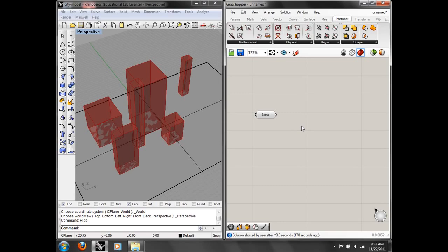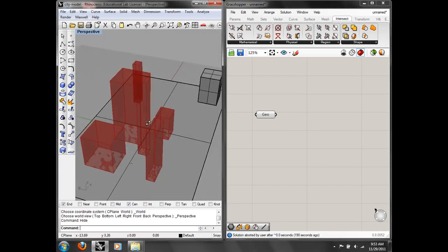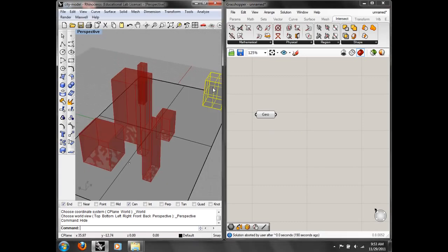So what we can do is look at those geometries, and get the highest z coordinate of each of those, and that's the height. Okay, because they all share the same base. Otherwise, we could get the lowest z coordinate and the highest z coordinate of each of these if they were on different planes, and you could subtract one from the other, and that would give you the height as well. So you've got to think of these as data. These are all boxes, so it would be very easy to figure that out because they're just kind of flat.